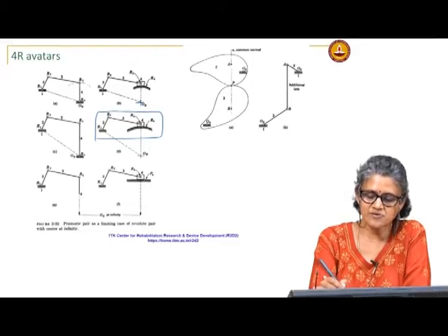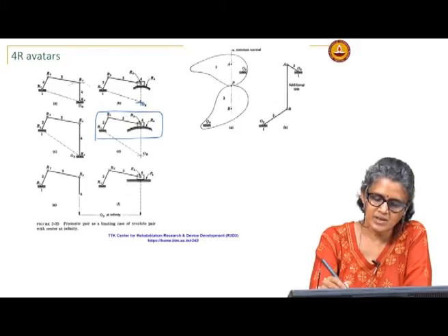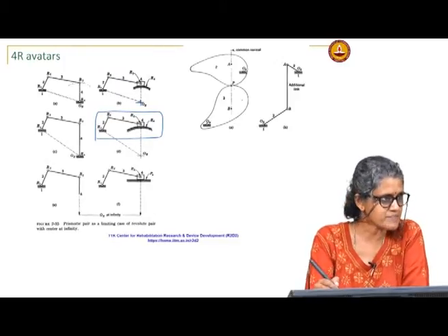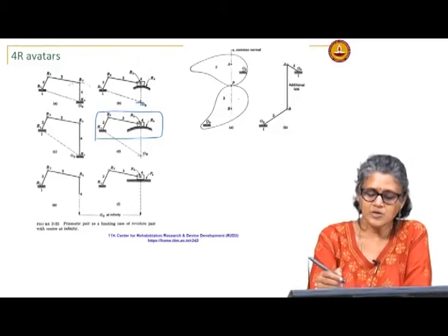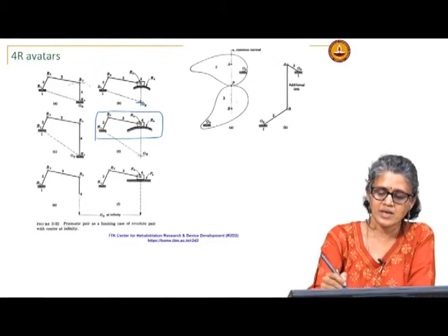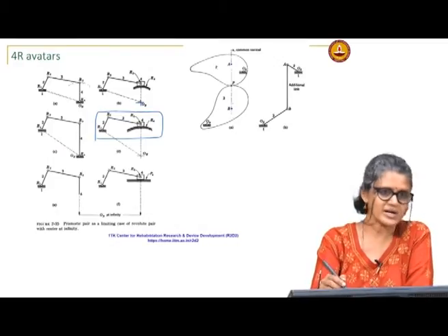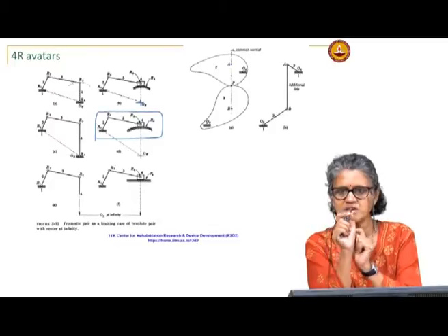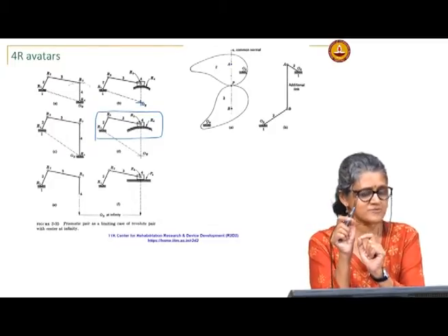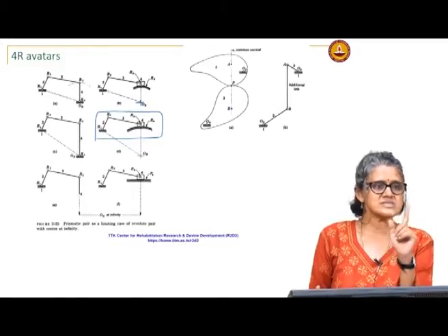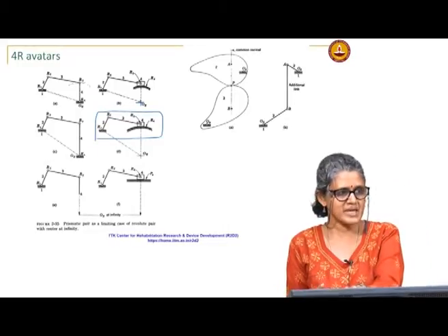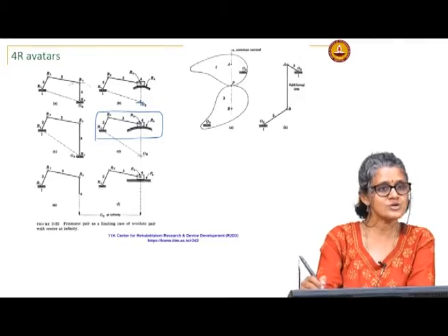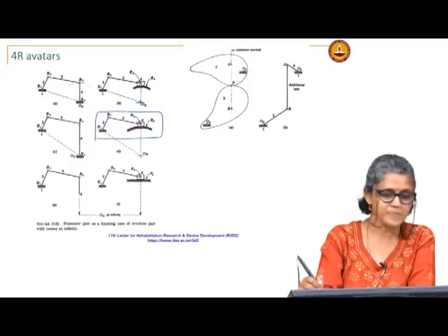So, if you look at the centers of curvature at the point of contact, say A is the center of curvature. So, P is the point of contact, and then B is the center of curvature of the other link at that particular instant. Okay. Now, the property of the center of curvature is such that if you draw the common normal at the point of contact, it will obviously pass through the centers of curvature. The centers of curvature do not change for 3 infinitesimal positions. Okay, that is a property of the center of curvature. And so, using that we can say that the velocities and accelerations of this mechanism will be equivalent. So, if I replace it with a link connecting the two centers of curvature along the common normal, then I get this 4 bar.